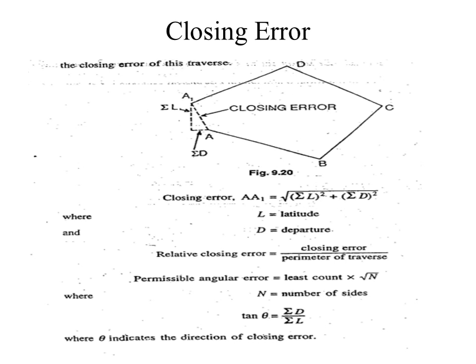Then the next check is auxiliary point. An auxiliary point P is suitably selected on one side of the traverse. Then magnetic bearing of this point are taken from A, D and F. If the traverse and plotting have been done accurately, then all these bearings must meet at P when plotted from the stations. The traverse can also be checked by calculating the coordinate of the point P, considering ADP and DFP as closed figures. If the coordinate of P calculated from both sides are equal, then the traverse may be assumed to be correct.